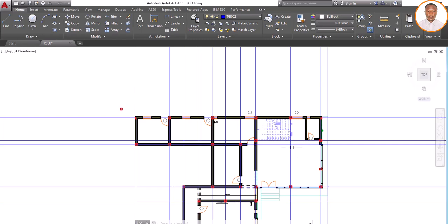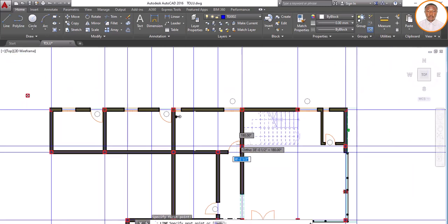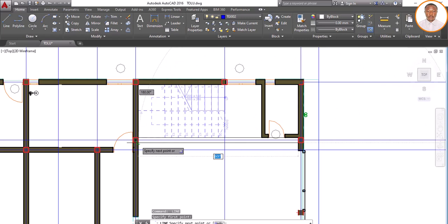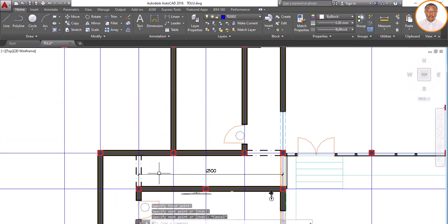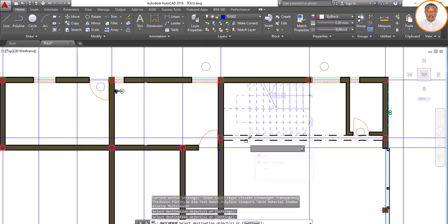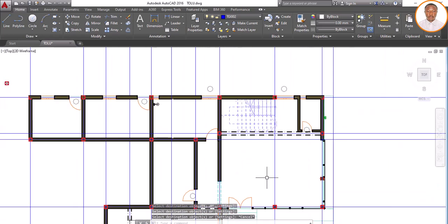So what I'm going to do now is show how my beam is going to run. This is our GA. So you can see it. We are doing our GA. Escape, enter, then click on this place again, and also at this place. So I come to this place and take the same property, copy the property, and come here and fix, which tells me that there is a beam running along that line. And this one from here to here is coming to land on this.